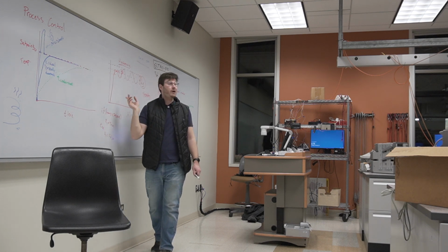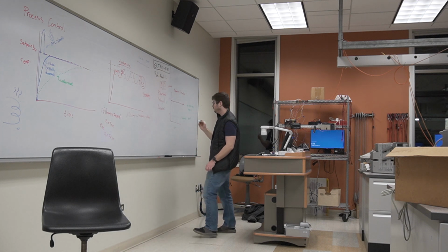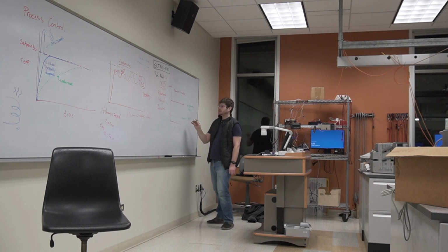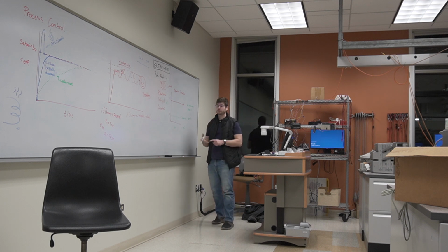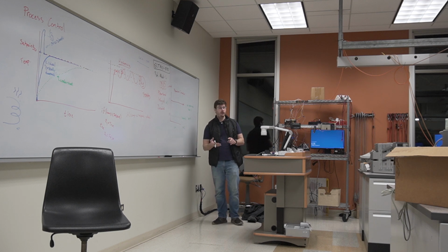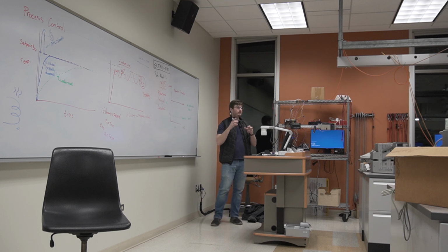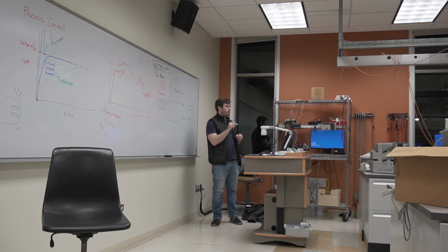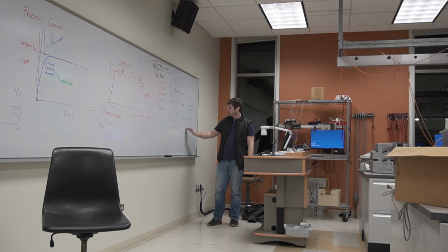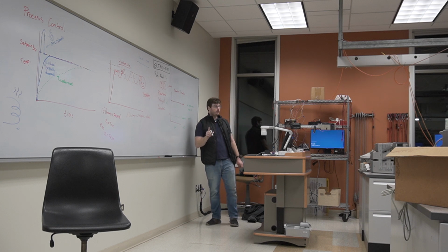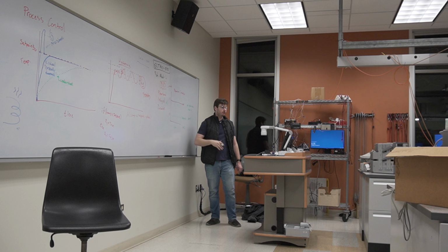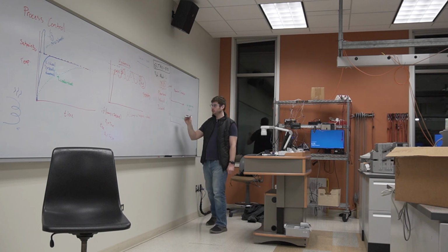And there's different effects that happen when that happens. Okay, but P in this case is whatever we want it to be. Okay, that's set by our code. So like in our structured text or in our ladder diagram, you would have a block that would be a PID block, and you would wire in 3 values to it, a P, an I, and a D. If we set P to 1, for every 1 error, it will try to correct with 1 amount of effort. You know, that might be turning your relay on or doing 1 unit of cooling.